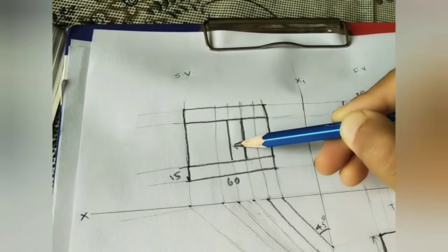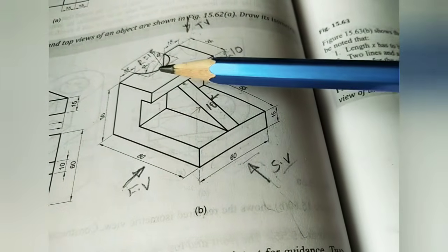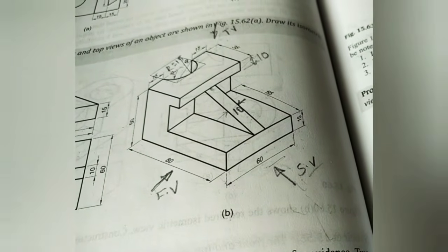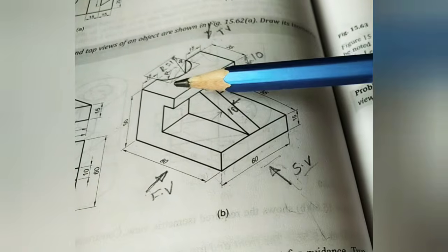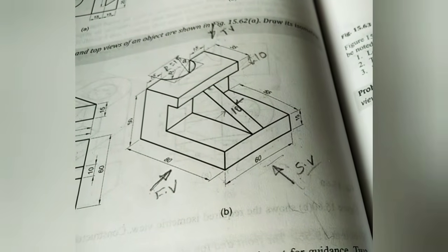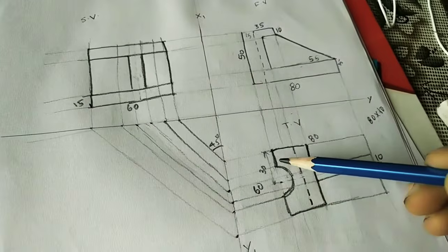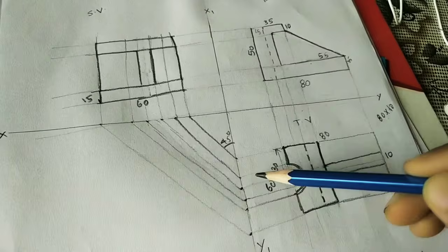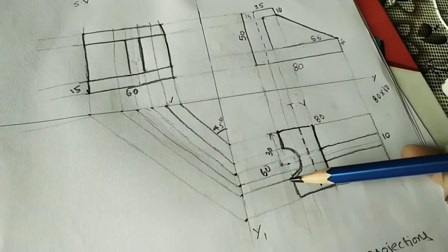Okay, it is 10. After getting this rectangle from the side view, we have to do this semicircle. This semicircle is invisible from the side view, but we have to show it in the side view. So for hidden parts we do the dotted line. This length we have already marked from the top view, wherever these lines are passing. So just taking a tick here on this line, and here this line.